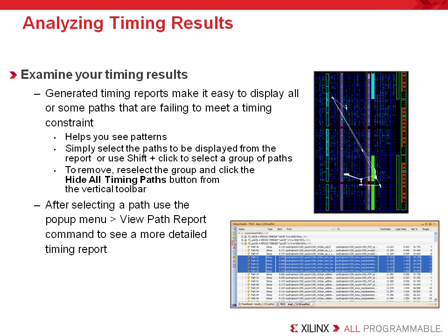You can analyze timing results from implementation to drive the floor planning effort. You can use the path sorting and selection techniques available in Timing Results view with the imported trace report data. Imported timing results sort the timing paths on a constraint by constraint basis. When you select paths in the Timing Results view, the Path Properties view shows the details of the timing path. Because the placement was imported, the path is highlighted in the device view. The visualization makes it easy to understand how to take appropriate floor planning steps to improve the timing.